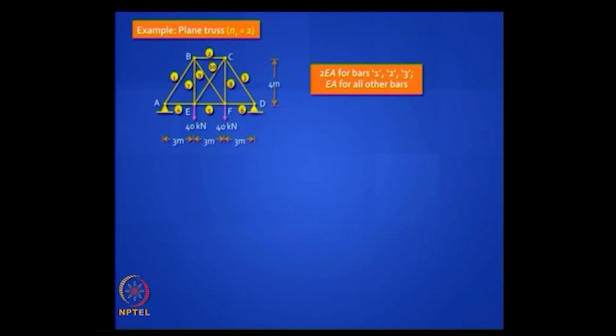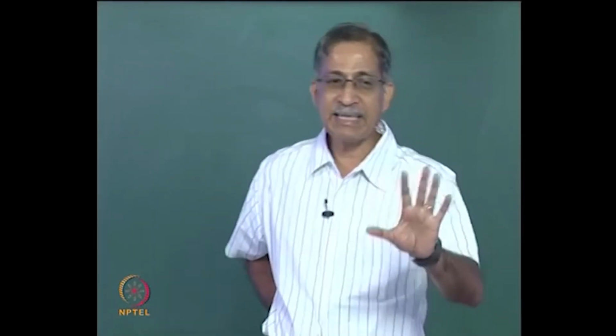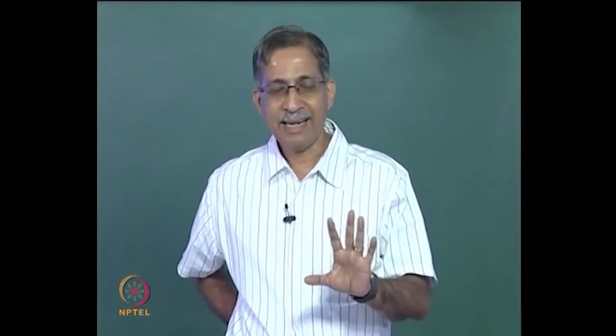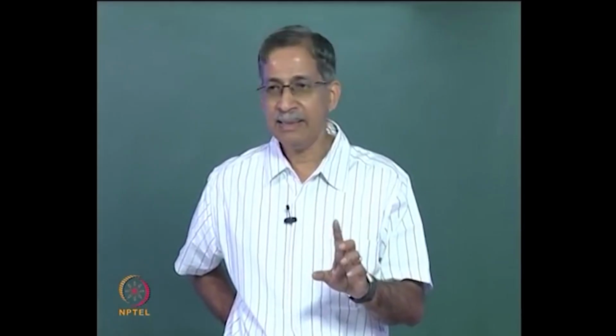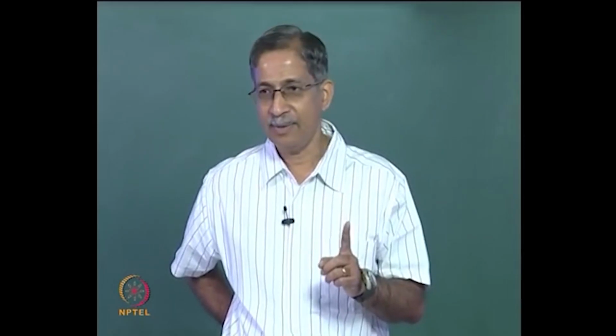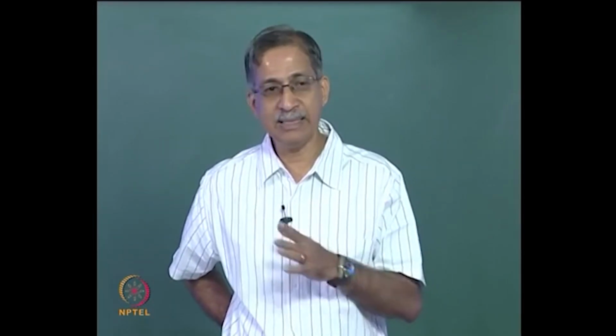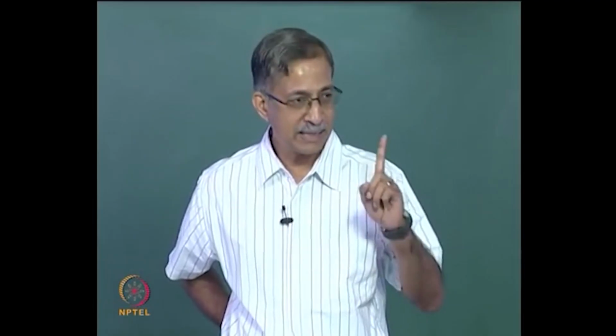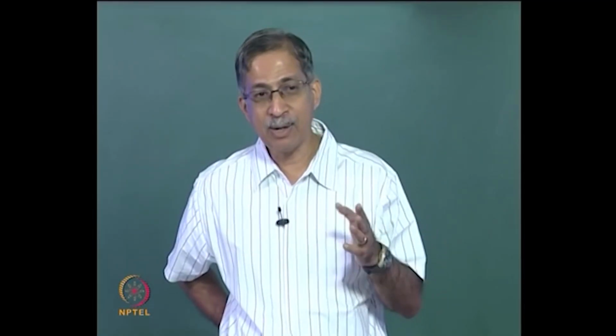If you take the example of a truss, here you have a truss with how many bars? 10 bars. Is it statically determinate or indeterminate? It is indeterminate. What is the degree of indeterminacy? Well, one look at that structure should tell you. First look at external indeterminacy. Externally you can view it as being not simply supported, so you got one extra redundant. If you make it simply supported, that means release a horizontal reaction. So one external indeterminacy.